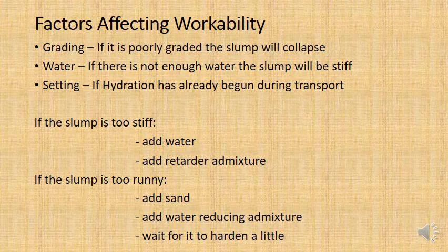So what do you do if the slump is too runny? What if you need to reduce the slump? Well, one of the first things you can do is add sand. Remember, if you've got excess water, sand will basically hold that water on the surface area, and so it would make it stiffer.